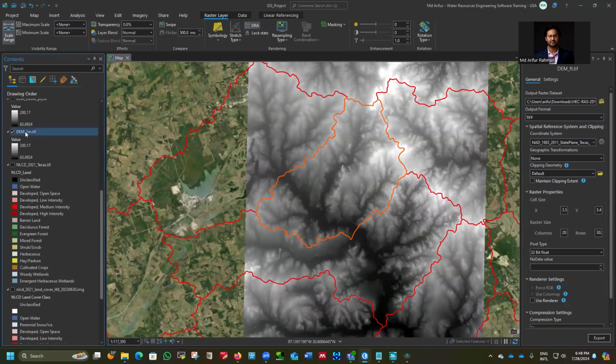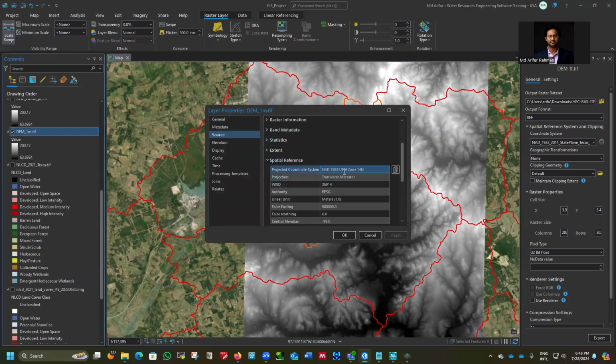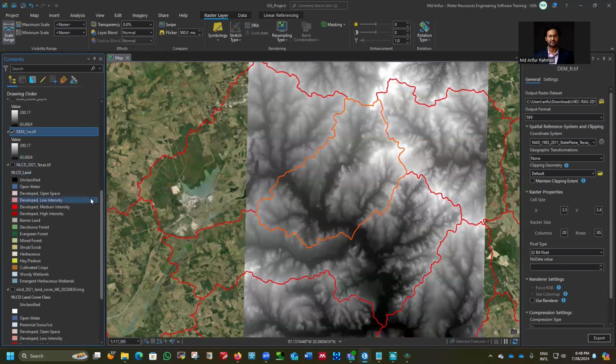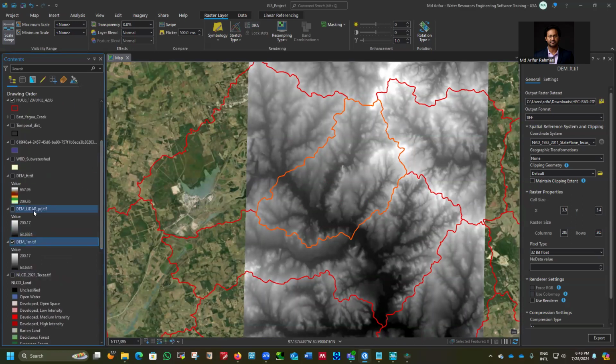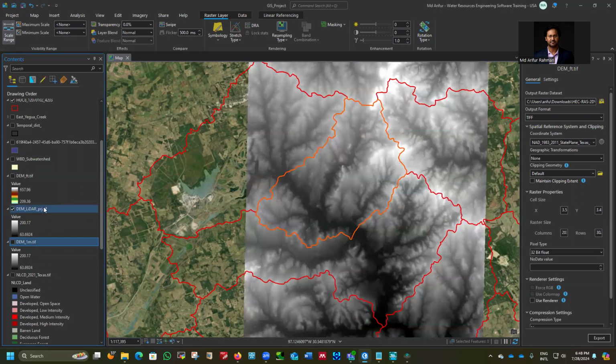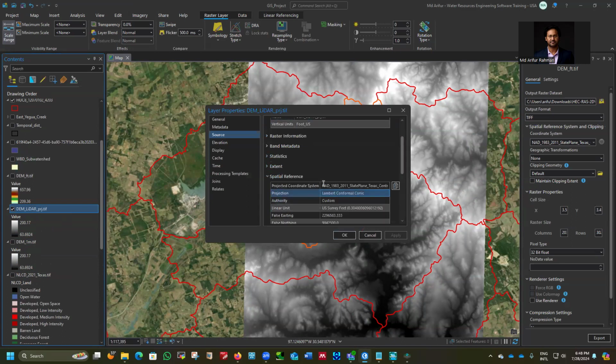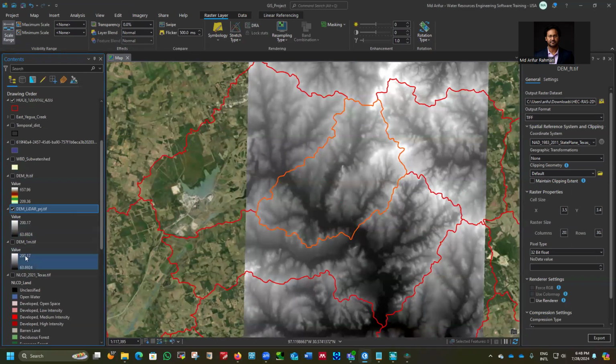And from there, because this is in the UTM coordinate system, we need to convert. If you want to check, you can check it's in UTM. So we need to convert it to a state plane. The first step is I converted the horizontal projection. I changed it to the same projection system we have, and you can see it's NAD 1983 State Plane FIPS 4203, but you can see we have the same vertical values. That means we need to convert the vertical elevation to feet as well.